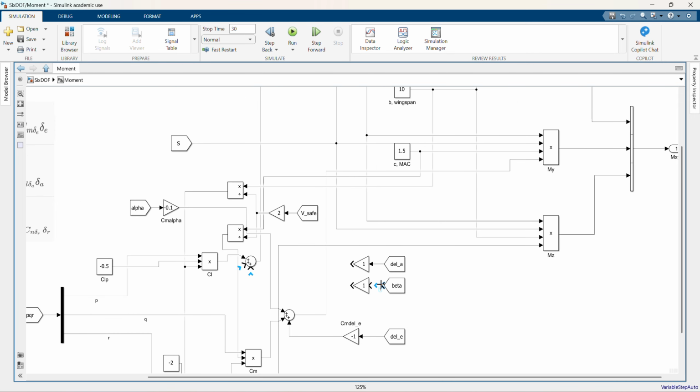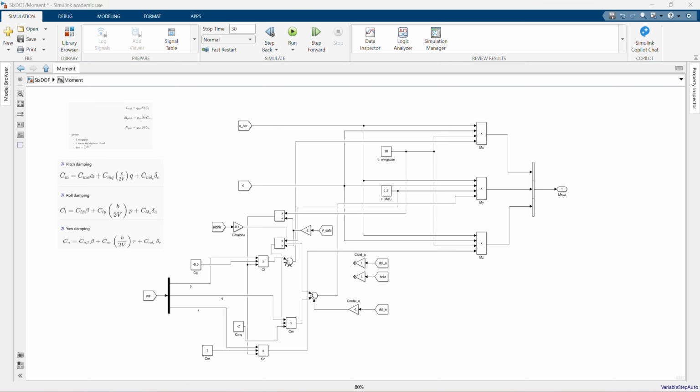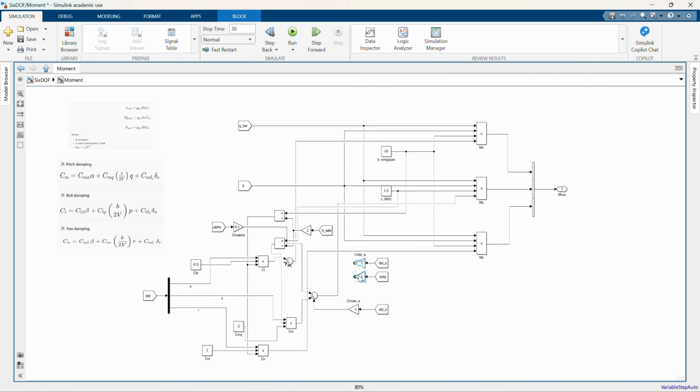This gain is going to be my CL del A. This is aileron effectiveness, as in how much rolling power you want to give to your ailerons. And this one is, I want to give some room there. CL beta. Okay. CL beta, the dihedral, and that connects to beta. Let's connect both of these. I did take care of both pretty well. So there we go, like that.